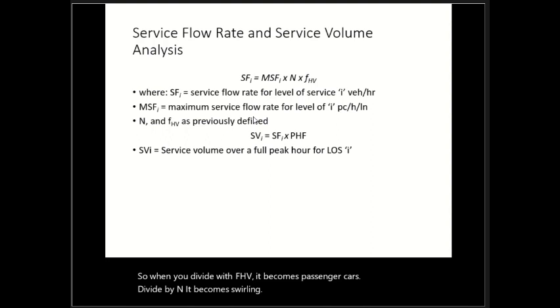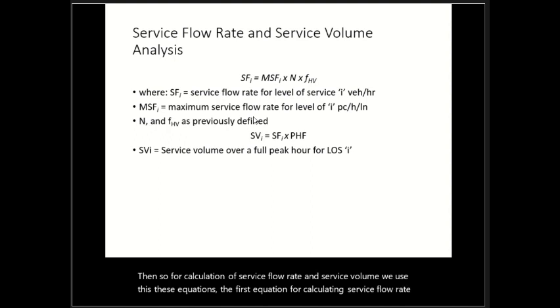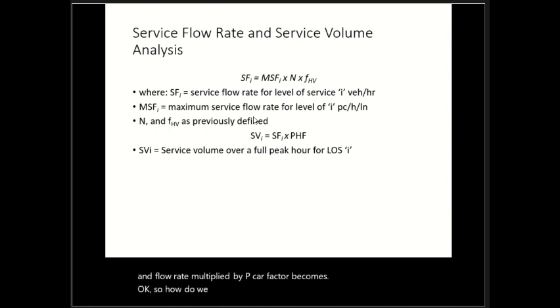Then, for calculation of service flow rate and service volume, we use these equations. The first equation is for calculating service flow rate, and flow rate multiplied by peak hour factor becomes volume. Okay, so how do we calculate service flow rate? So you can see N and fHV already explained, right? The only thing here to be explained is MSF,